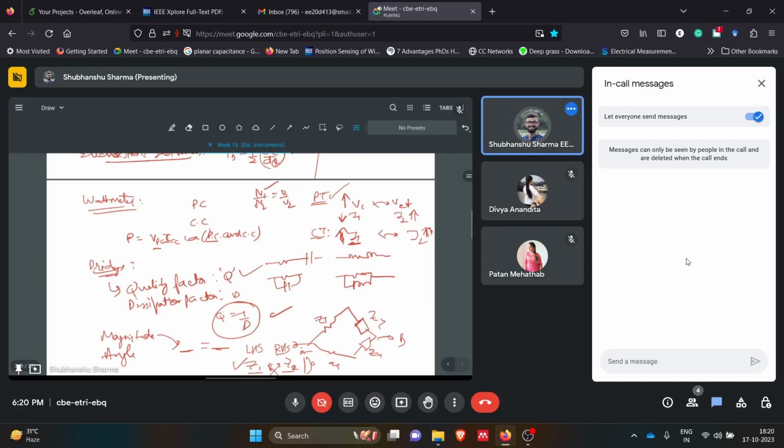I have given you those questions in the live session, and we have practiced some of them, which had a BJT or diode-type elements in the feedback, and how to solve them. So in operational amplifiers, the first thing to look for is what feedback there is: is it a comparator, or if a feedback is there, is it negative feedback or positive feedback? If it is a negative feedback system, then no need to worry, you can solve with the virtual short concept, and you can use KCL, KVL, whatever.